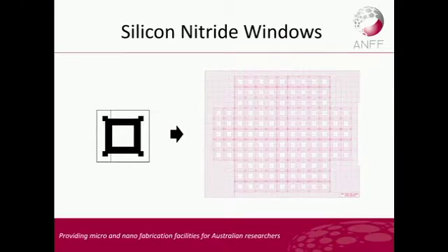This time we're using wet etching, so KOH at temperature to etch through the silicon. So we generate our mask. Again, it's important to have a frame that the devices sit in, because you don't want to etch and then for the whole thing just to collapse at the end of it and fall apart inside the wet bench.